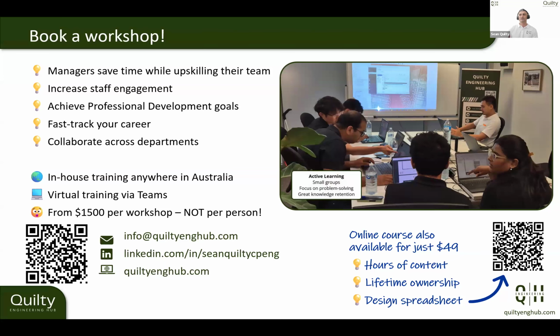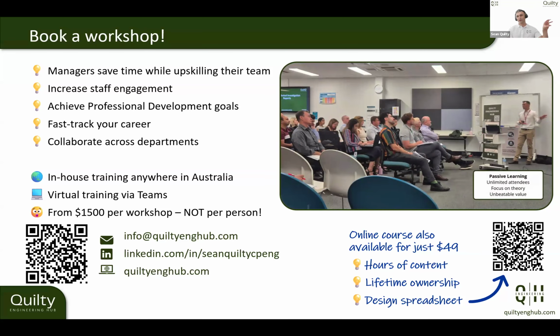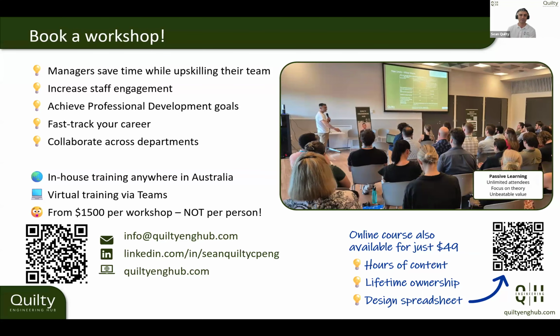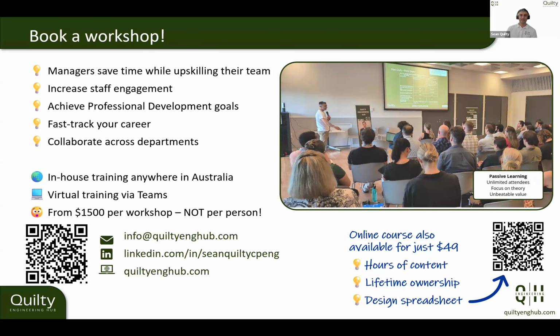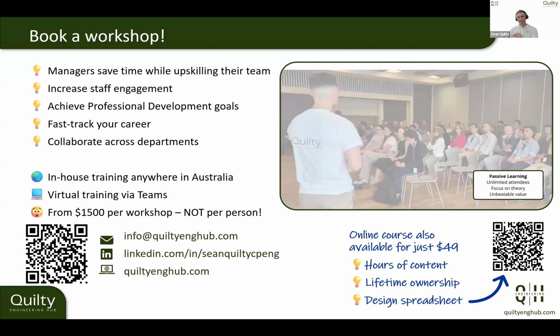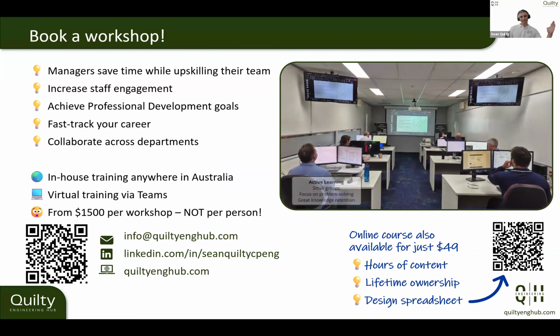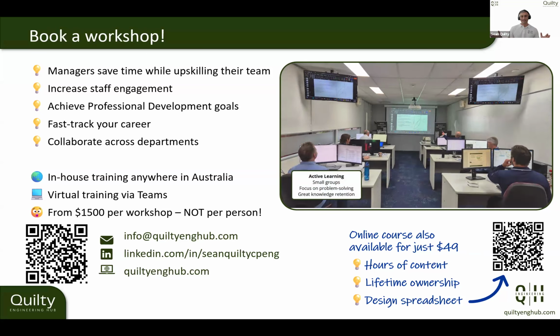And we also are finding that our storms are going to be more front loaded. So you're going to have that peak early on in the storm rather than a mid-loaded storm. So I would say that part of that strategy would also be accounting for what might happen with climate change. And that isn't just a specific value or a table you look up, but it's actually a spectrum. It can be, well, if it's not as bad as what we think, you'll be down here. If it's really bad and worse than we think, it'll be here.